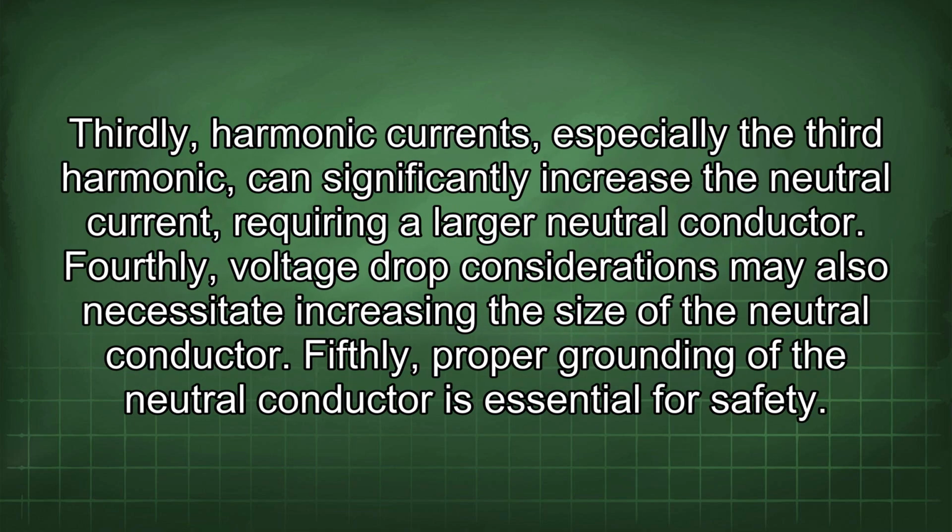Thirdly, harmonic currents, especially the third harmonic, can significantly increase the neutral current, requiring a larger neutral conductor. Fourthly, voltage drop considerations may also necessitate increasing the size of the neutral conductor. Fifthly, proper grounding of the neutral conductor is essential for safety.